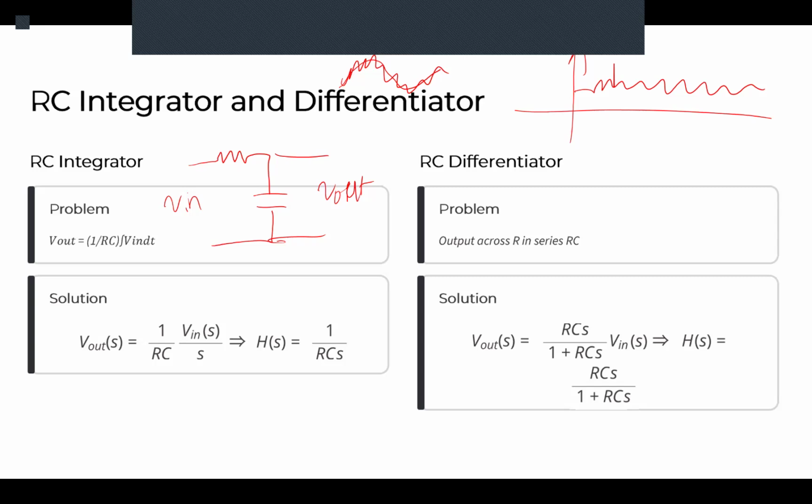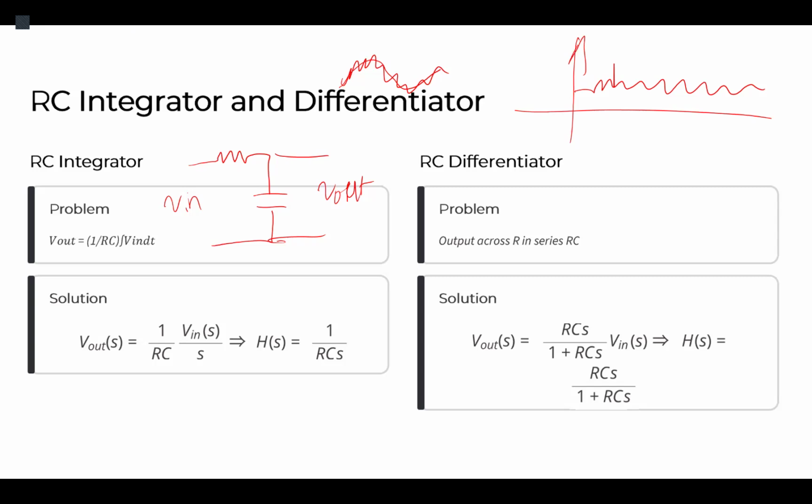How do you calculate that DC from that haphazard signal? You take the average, correct? You average out the variations. So you have the main signal. What mathematical operator does the averaging? Integral. So a low pass filter is an integrator. Eliminating the variations gives you the averaged signal. Are we good? Yes.